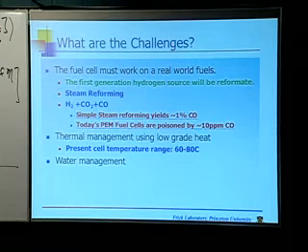You can get this number down by doing things like doing two-stage reforming and adding in a water-gas shift reaction. And you probably want to do some of that anyway, for example, the water-gas shift, because that CO is a fairly energy-rich molecule, and you would like to get more hydrogen out of it. So 1% is on the high side, and you're probably not going to deal with that. But even having said that, you're not getting down to 10 parts per million by doing all those things.